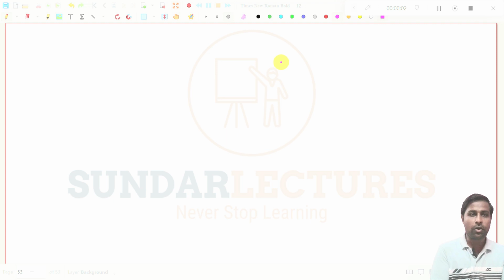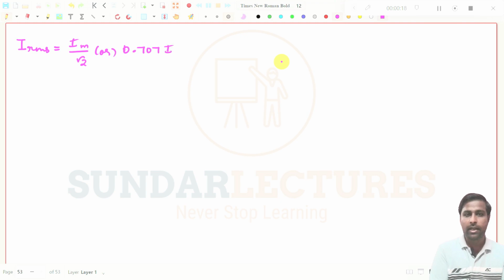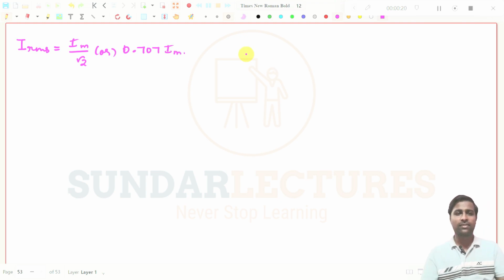So now we know, right? What is that? IRMS, which is equal to Im by root 2, or we can write it as 0.707 Im. So this is the formula now. What is Im here? Im is nothing but the maximum value. So we have already seen this.